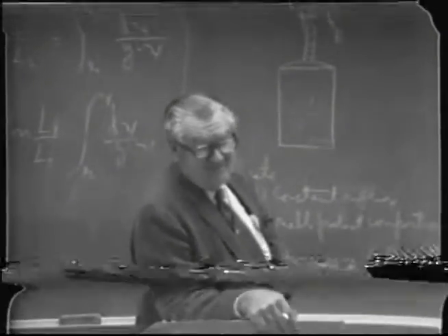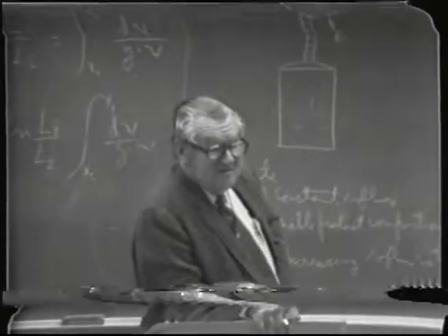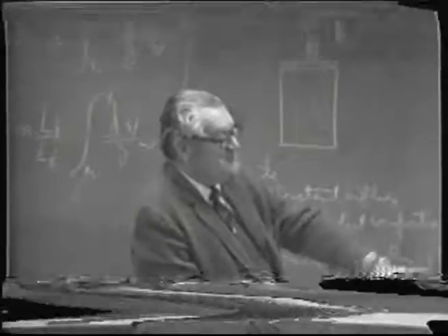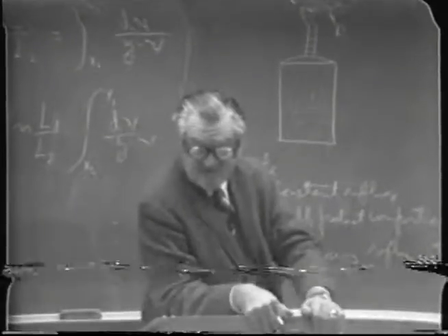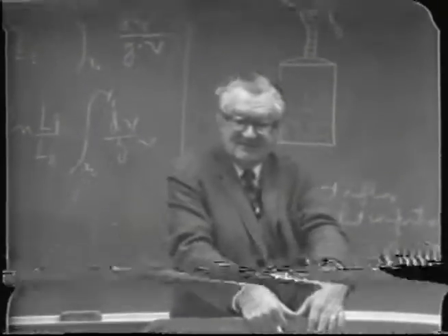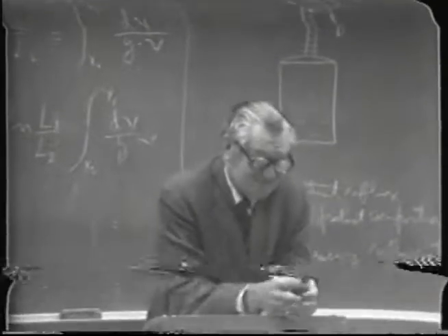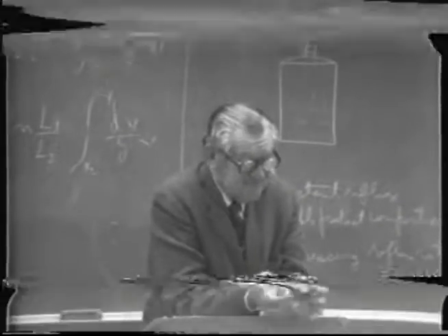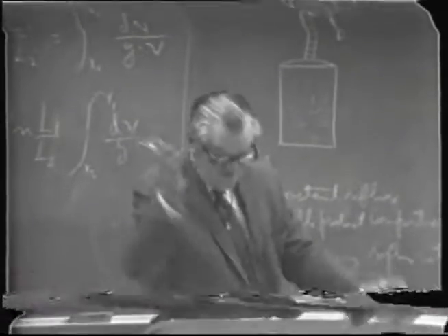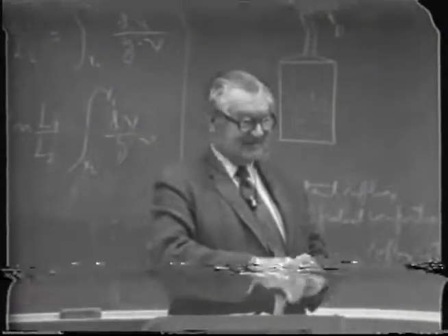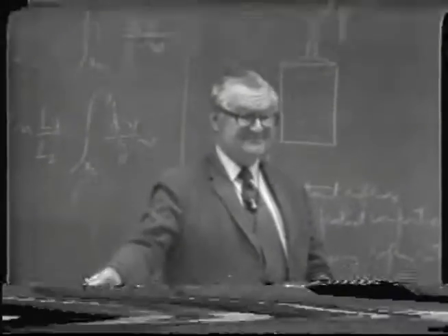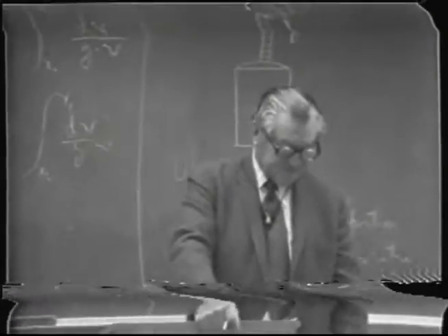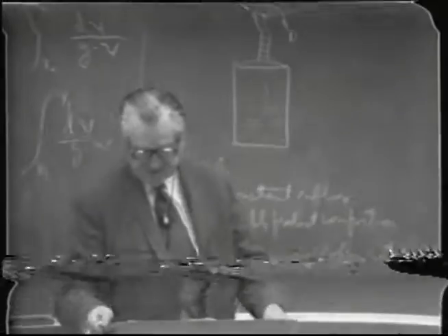So let's say they're maybe 170 proof. And then you'd carry along at more or less constant reflux ratio for a variable length of time until it's obvious that you're not going to be able to hold that much longer. You have to have too high a reflux ratio. Well, then you'd cut it off and collect the tails portion, and then probably decrease the reflux ratio so you'd get the tails over more quickly, where you're not interested now in holding the concentration up.